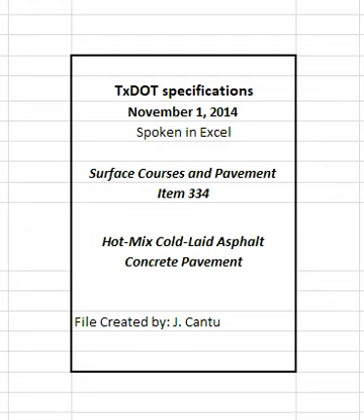The engineer may require rolling with a trench roller on widened areas, in trenches, and in other limited areas. Allow the compacted pavement to cool to 160 degrees Fahrenheit or lower before opening to traffic unless otherwise directed. Sprinkle the finished mat with water or lime water, when directed, to expedite opening the roadway to traffic.